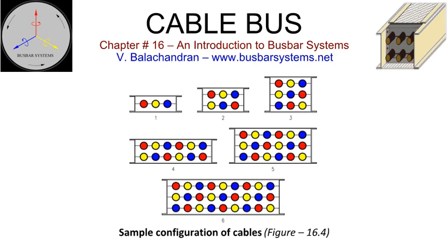Hanger, wall and ground supports. The cable bus products are light and are supported by hanger rods from the ceiling or brackets from the wall for the indoor sections. It is the industrial norm that the support span should not exceed 6 meters, 20 feet. Outdoor sections are supported on standard T or H frames depending upon the elevation of the run. Cable bus shall not be considered as a structural member.